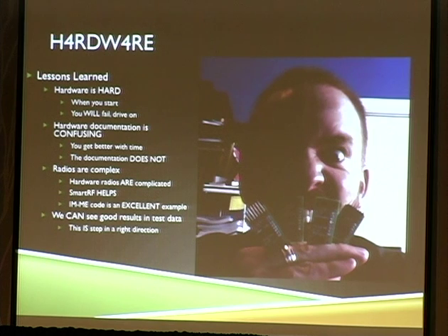Hardware documentation, I mean, they hammered it. Whenever I asked for help, when I talked to Travis, when I talked to Q, when I talked to Atlas, it was, did you read the docs? Yes, I read the docs. How many times was it actually a wiring issue? Do you have it wired right? Yeah, of course. And for that one wiring issue, how many times do you say, yeah, done that? No, done that. And then I read the documentation, and I realized that I flipped the pins, so pin 1 was actually pin 10. So, number 1, read the frickin' documentation.